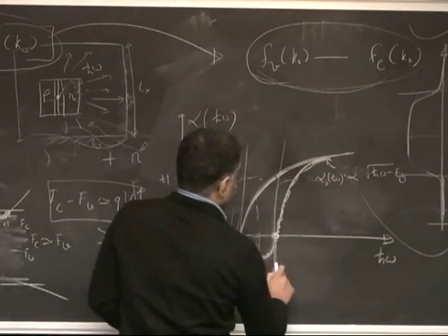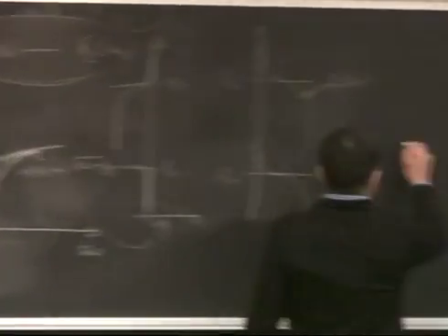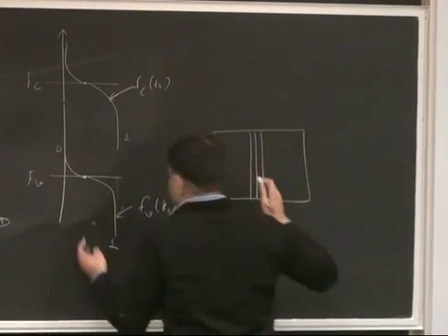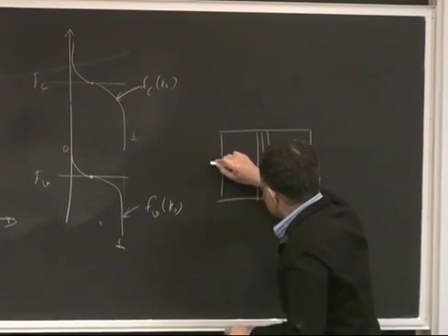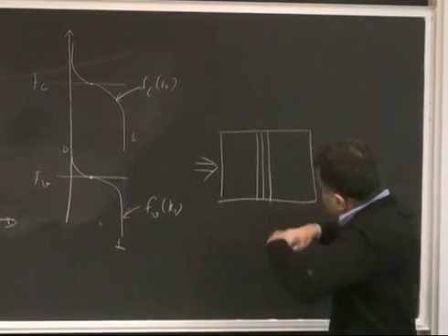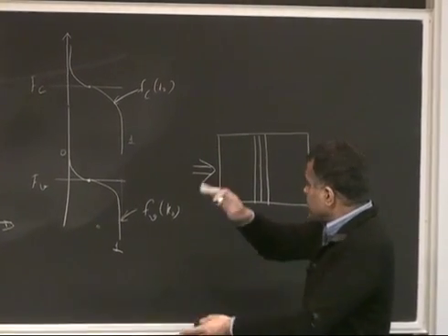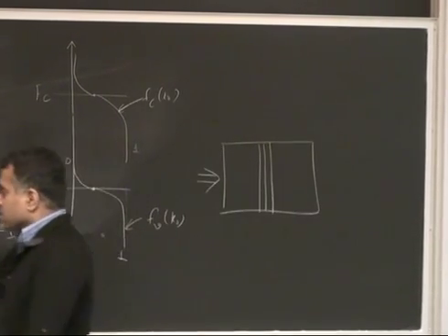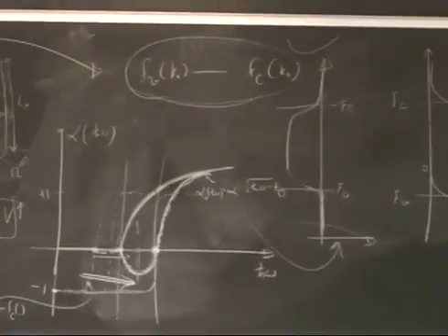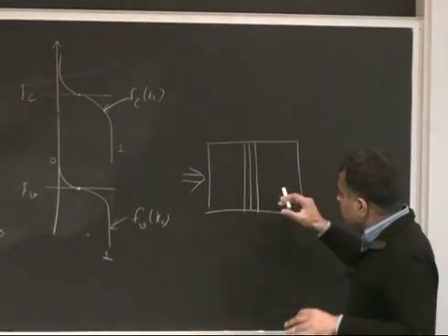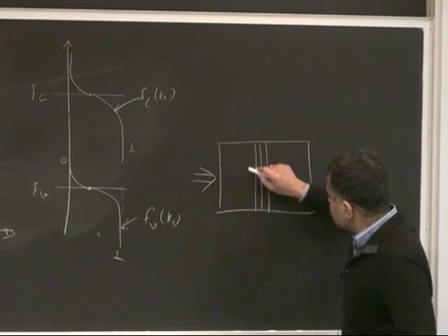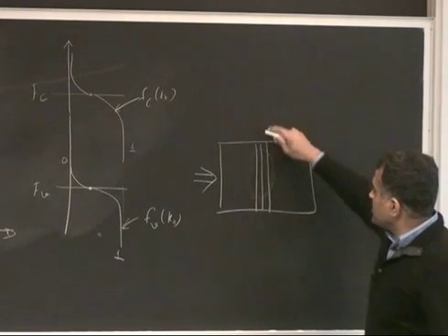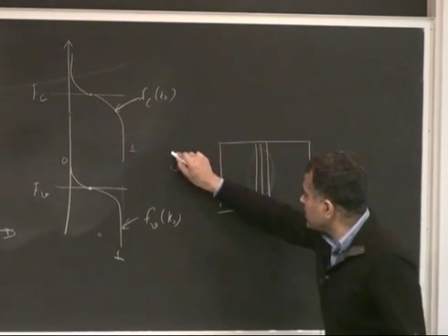What have we done? We have basically taken a PN diode now with some quantum wells in the active region. Right now all we have done is we have injected a lot of current into it, applying a certain large voltage to split the Fermi levels, and then there is some amount of gain of the light that's coming out here. If you take this same semiconductor under this situation, this region where the light is being generated is in a very strange state, because this is current injection.